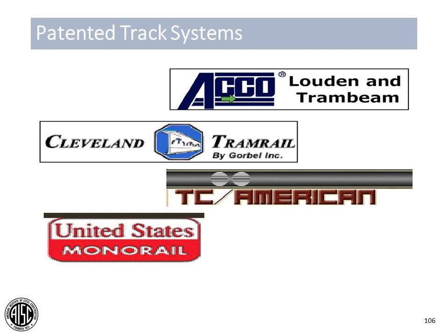So that would be if you're looking at a buffer end stop, or the preferred method would be if the crane supplier can specify that. If you have that information early on in the design, the crane manufacturer may prefer a specific type of bumper system, and they'll know the rated speed for their end trucks. So they may specify an end stop force, and if you have a crane supplier early on, they should be able to provide you with that information.